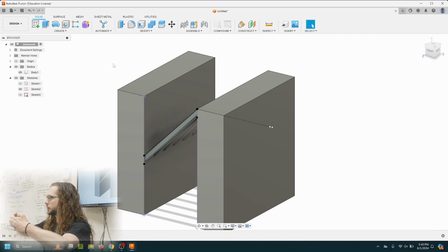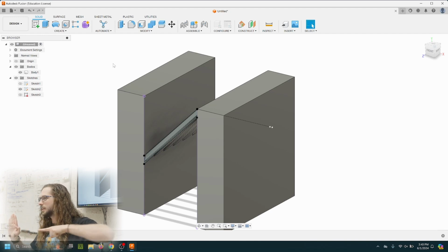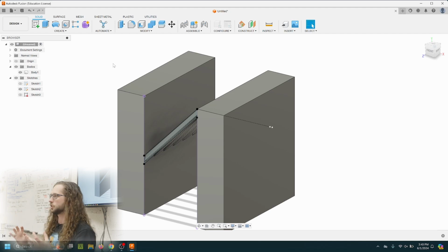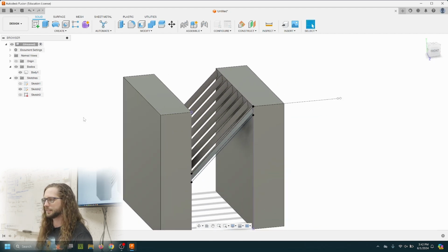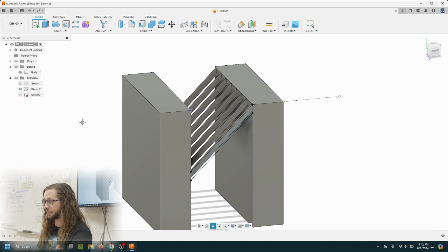And for example, if you're trying to do this onto a cylinder, there's no way that you could have a plane that is touching in a 3-dimensional way on a cylinder. So just have that path extend into the cylinder and then use join so that you get all the way up to the edges of the cylinder. And so we can do that. Let's do that instead of a curved path. I think you can understand what a curved path is just to explain it using Fusion.